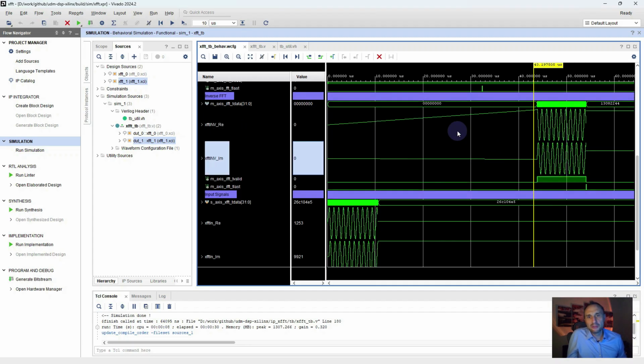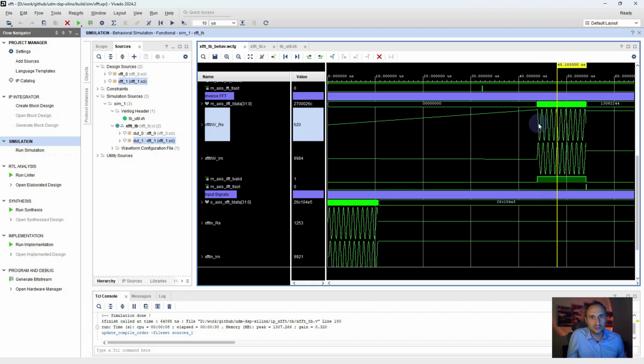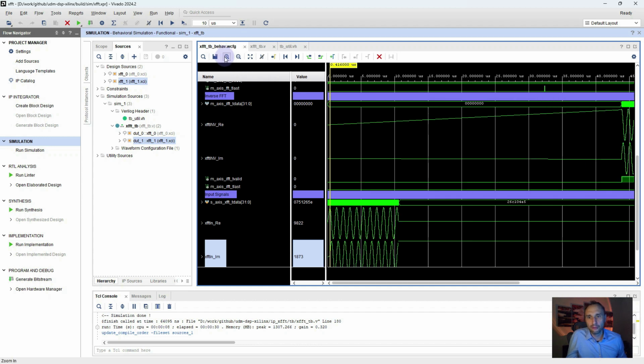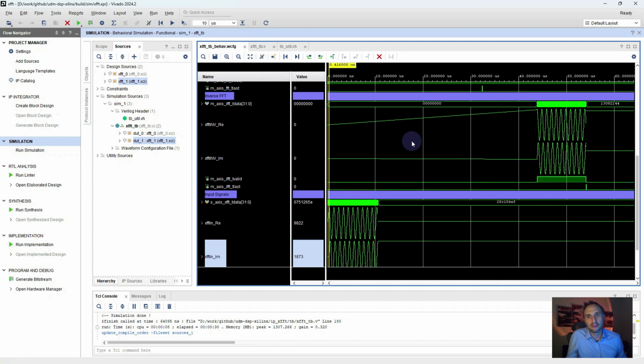So what can be seen here? Here it can be seen that the signal remains the same with the same phase. So it's for real time. This is a cosinus that starts with the maximum amplitude, or let's say with unit 1. And the sinus starts with a 0. So it's completely the same as I have for my input signal. So it means that there is no phase distortion during the FFT in both directions.